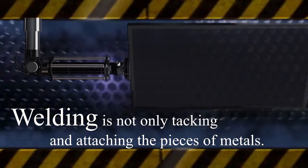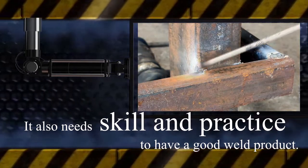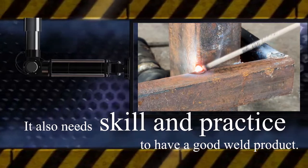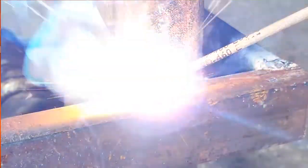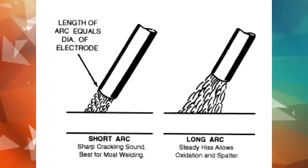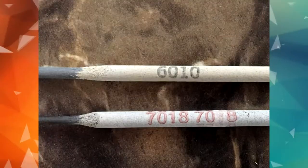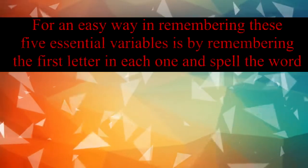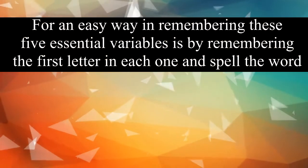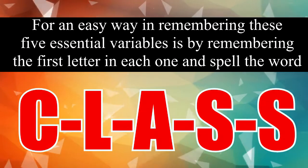Welding is not only about tacking and attaching pieces of metals. It also needs skills and practice to have a good weld product. There are things that we have to consider in order to have a quality weld product. These are current setting, length of arc, angle of electrode, speed of travel, and selection of electrode. For an easy way in remembering these 5 essential variables is by remembering the first letter in each one and spell the word CLASS. Let's discuss this one by one.